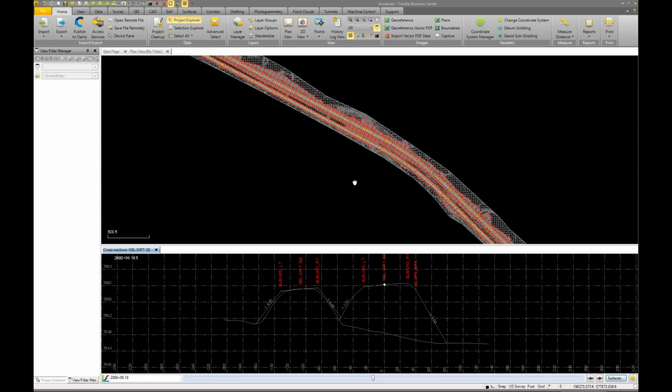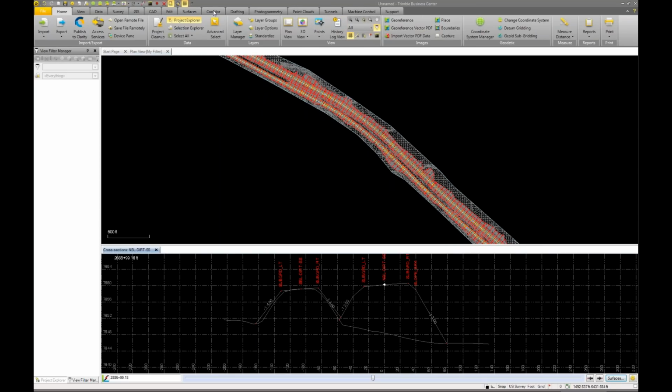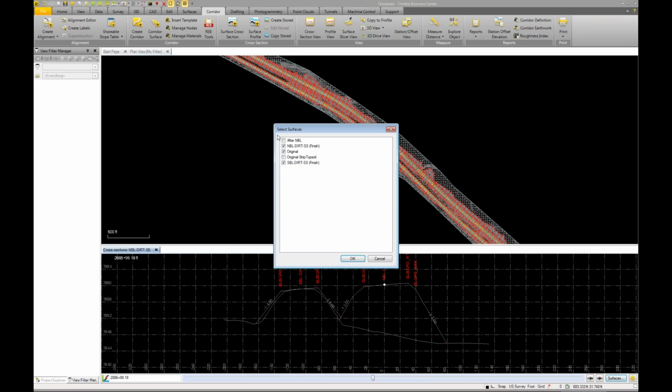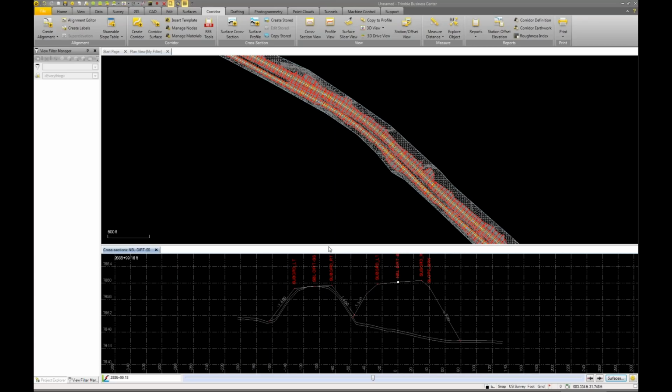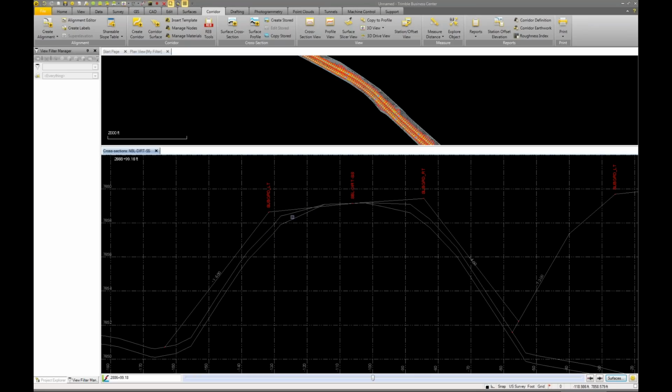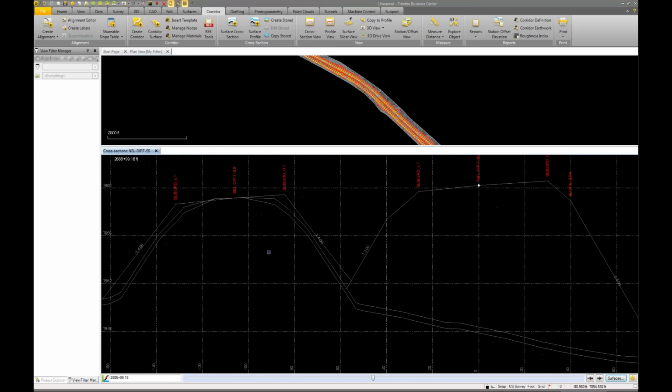And what this looks like, I am going to go back into my cross-section view here, and I'll turn this surface on so we can see what this looks like. So this is the surface that is basically, we've offset it, in this case about half a foot down, representing where we have stripped topsoil in that model, and where we don't strip it is where we have sections of existing pavement. For example, where this existing roadway was, there is no topsoil stripping, but the rest of the project we do have that.